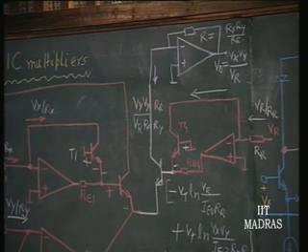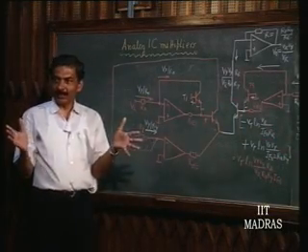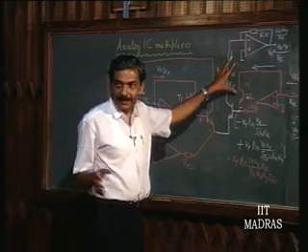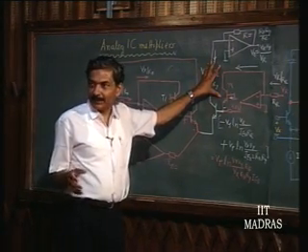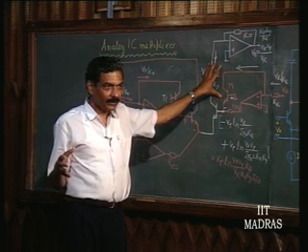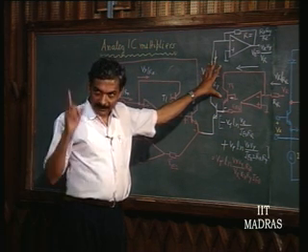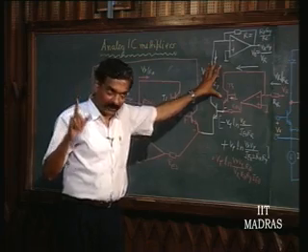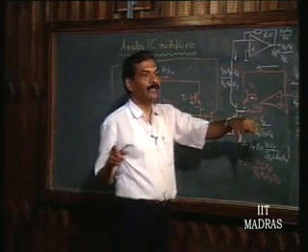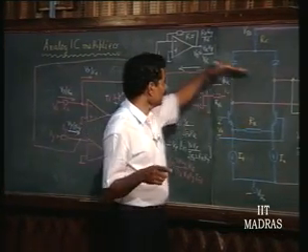So you get a precision multiplier which is totally independent of I_E0, as long as all the transistors have the same I_E0. That is why this is a very cheap multiplier, a precision multiplier but cheap, single quadrant, because V_x, V_y and V_r have been assumed to be positive, so that the current is only in this direction.